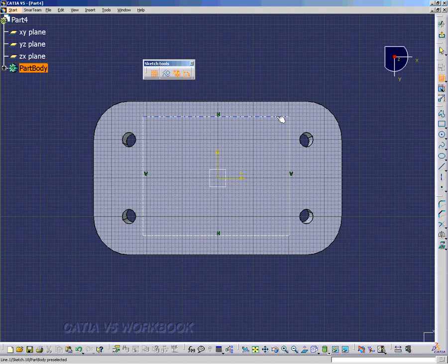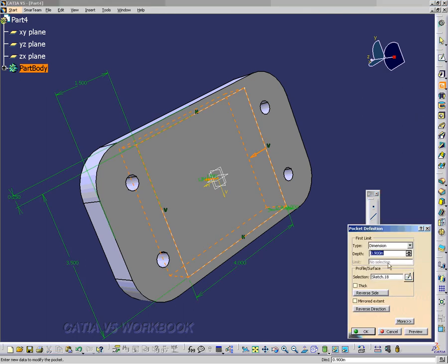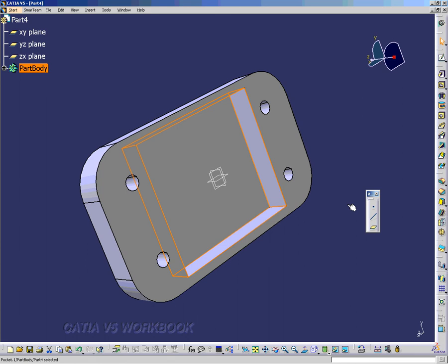And now we're going to center it. Or actually, let's make the parameter from the bottom to the bottom of the actual housing be 0.25, so that'll shift it up a little bit. And this parameter here will make 1.5 inches, so that kind of centers it. And then we'll exit out and we'll create a pocket, and we want the depth to be 0.75 inches. There we have our pocket.